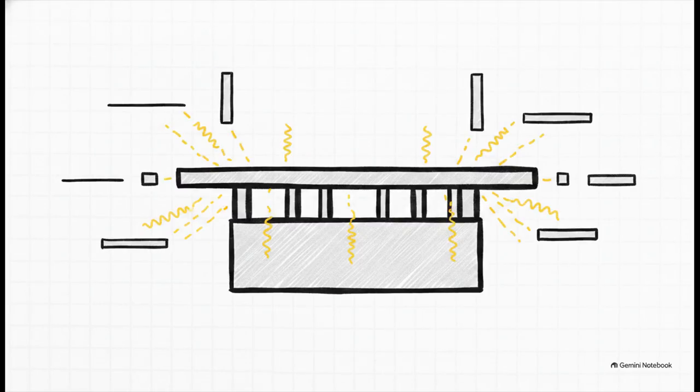But a wire doesn't just resist flow. It also acts like a microscopic sponge that stores electrical charge. That's capacitance. It exists basically anytime you have conductors separated by an insulator. Inside a microchip, a metal wire has capacitance to the substrate below it, the layers above it, and the wires running right next to it. And since a larger capacitance requires a lot more charge to actually change its voltage, high capacitance means your signal is going to be significantly slower.